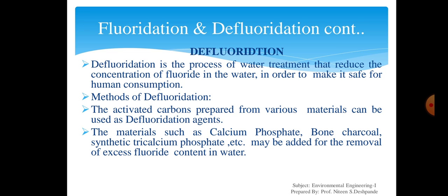In contact with water, bone charcoal is able, to a limited extent, to absorb a wide range of pollutants such as color, taste and odor components. Moreover, bone charcoal has a good ability to absorb fluoride from the water. This is believed to be due to its chemical composition, mainly hydroxyapatite, that is Ca10(PO4)6(OH)2, where one or both of the hydroxyl groups can be replaced with fluorine.